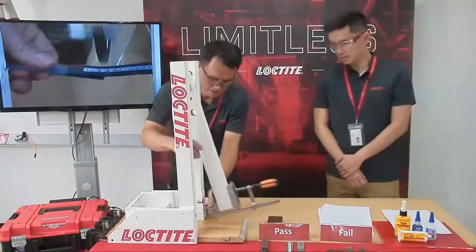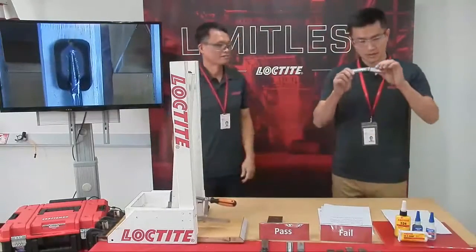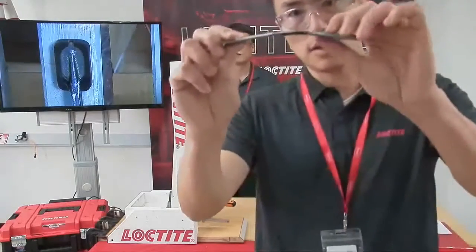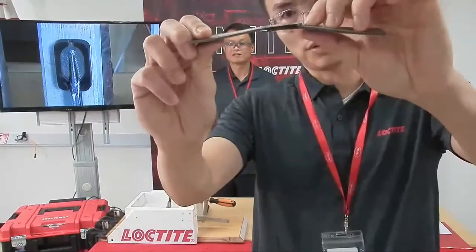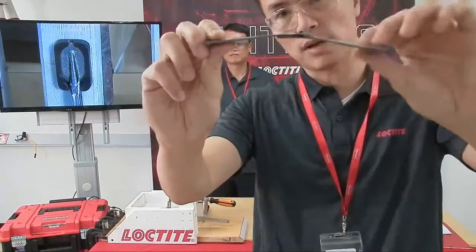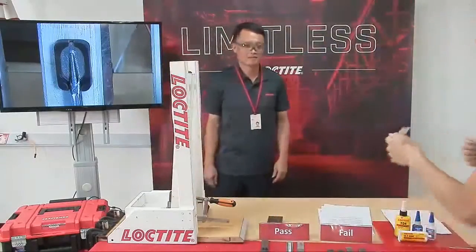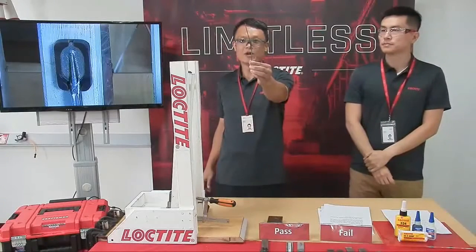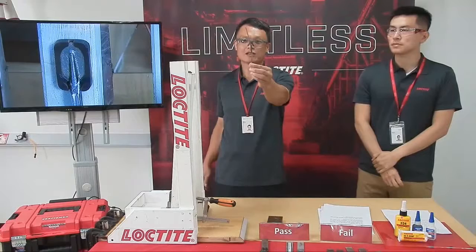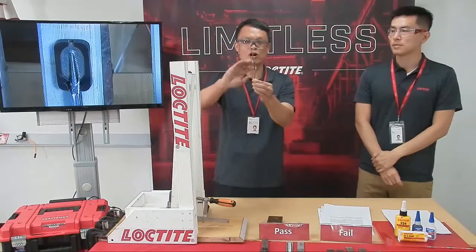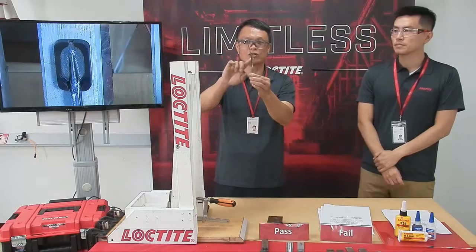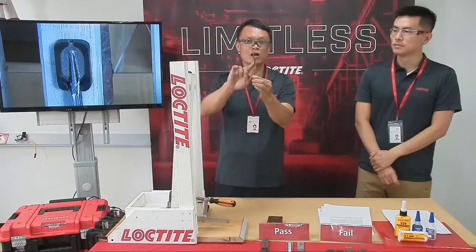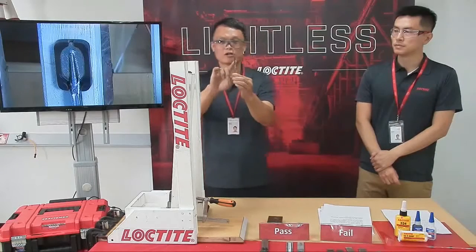Wow, it's a very strong CA. I'm not sure if you can see it, but there's only a little bit of separation between the two substrates, and most of the parts are still stuck together. Yes. If you notice the deformation of the substrate, it means that stress starts to distribute evenly to the whole structure. It's not concentrated on the joint only. So it's not like the failure mode we have seen on the joint done by welding.